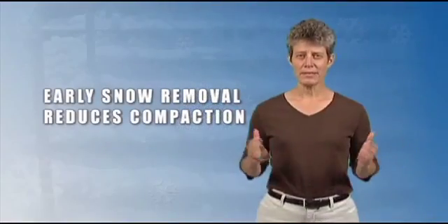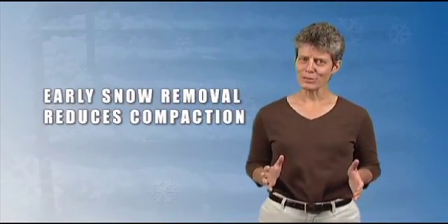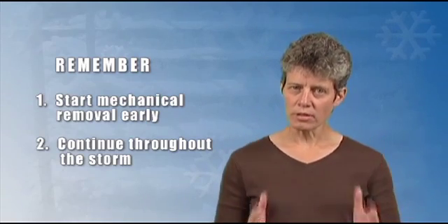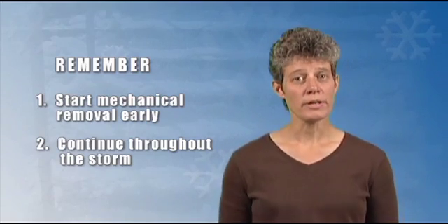If you're always battling compacted snow, reassess your maintenance strategy. #1, start mechanical removal early. #2, work it all through the storm. Remember, mechanical removal is your first defense.